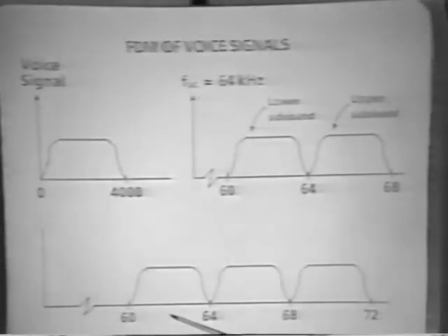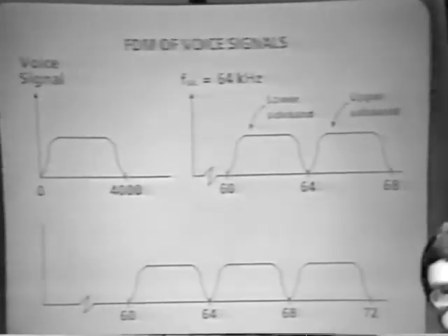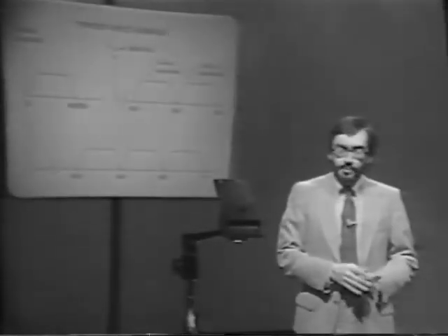And so in this fashion, depending on the bandwidth of the line, you can get whatever that bandwidth is divided by 4 kilohertz, and that tells you how many voice channels can be simultaneously carried. Now, standards have actually been created for this. There is a convention that is used. It was initially set up by AT&T, but it is also used by the other private carriers. And there's a similar standard used in Japan and Europe and the rest of the world.